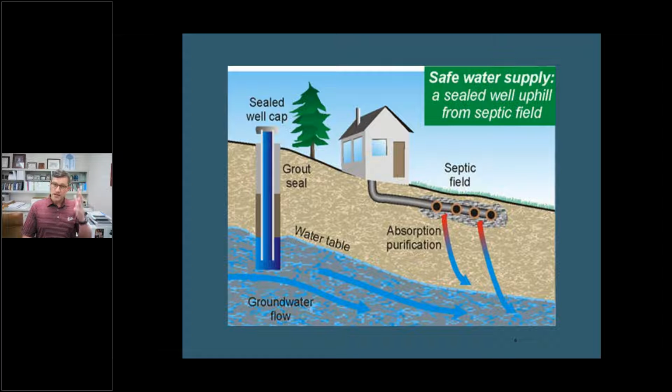And if you can, knowing if there is a general aquifer flow in your area, a lot of our places in Mississippi, we see this general northeast to southwest flow of underground. So when we think about placement of wells, we may put the well in a northern or northeastern location, depending on the septic. Just trying to think about the separation and the movement of anything underground, but also thinking about what you put into the septic tank, making sure that it's not impacting the groundwater. So just trying to give that cross section so people start understanding what we have and the processes of that.